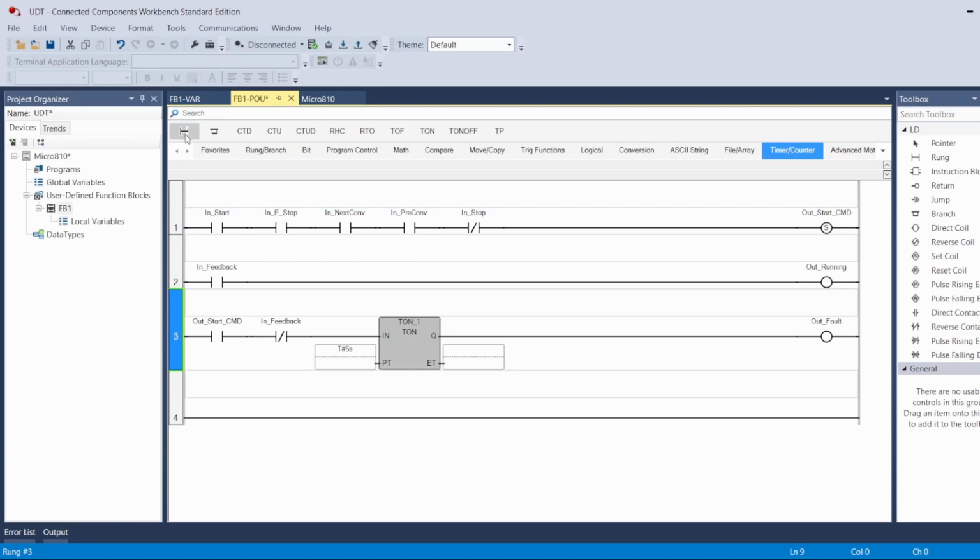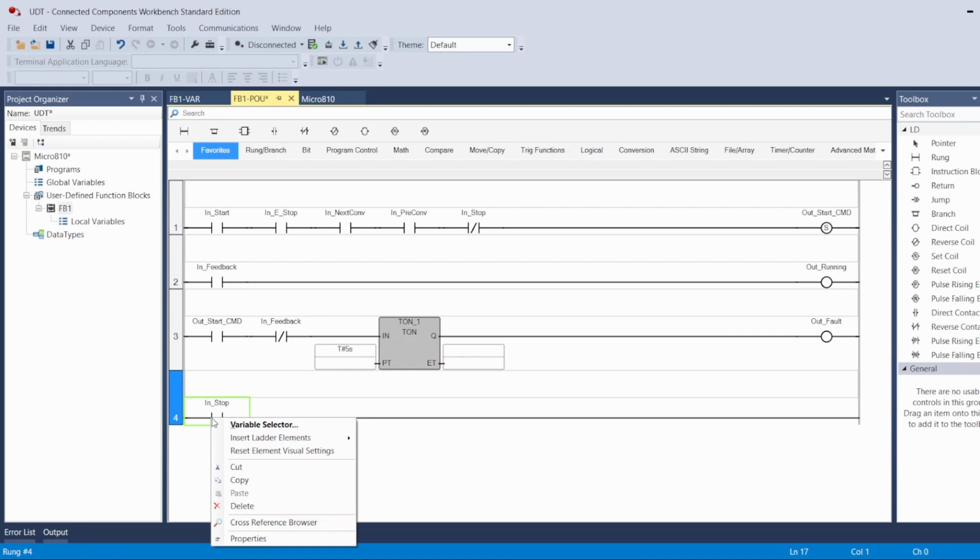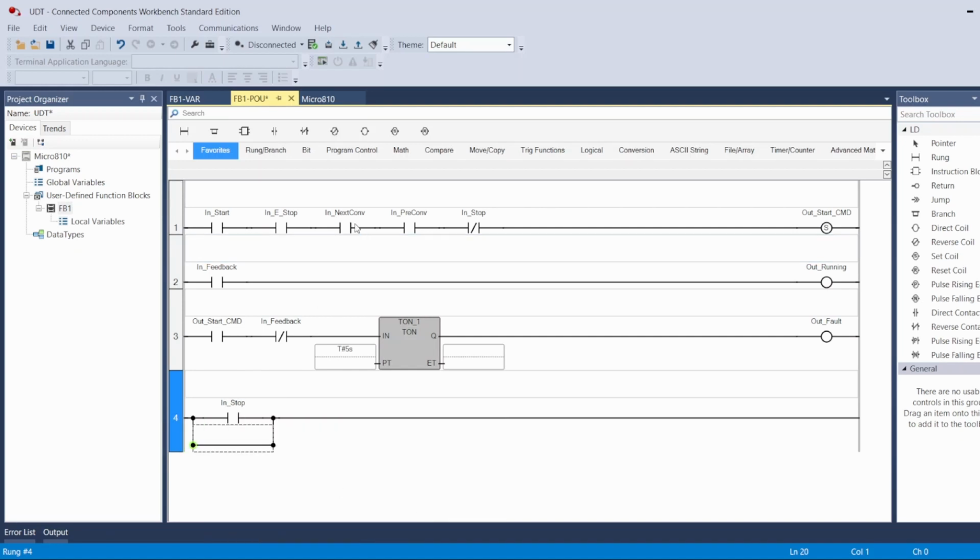And here the last thing is if we want to turn off the motor by pressing stop, for example. So let's go back here, highlight it here. If I press stop, or also the e-stop circuit is not satisfied anymore, so I don't see the e-stop input anymore.